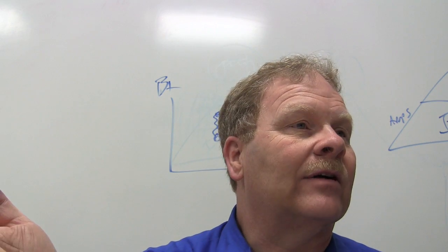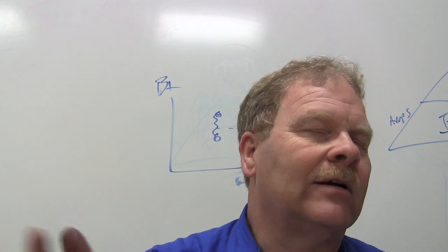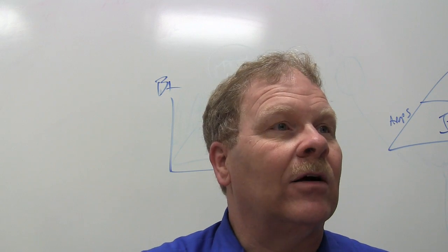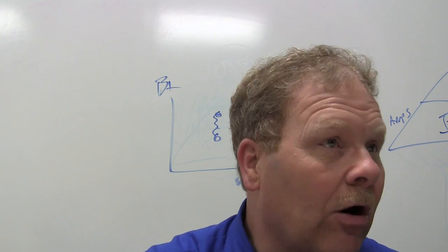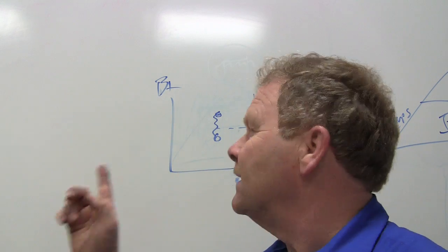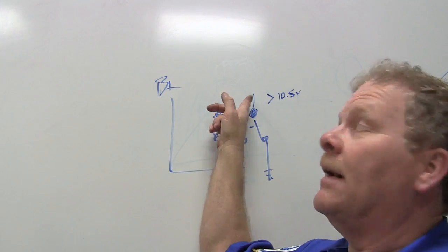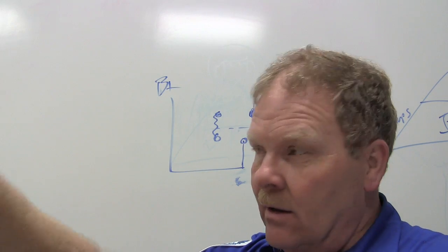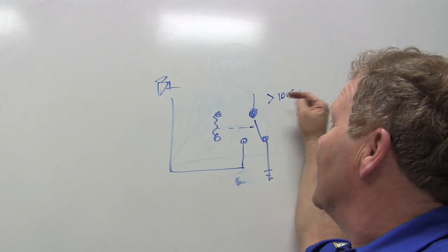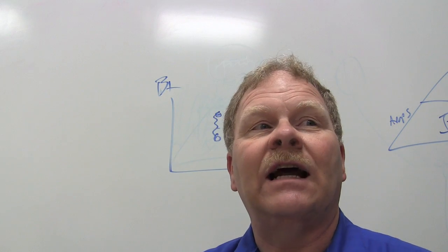And I went all the way to the end of that trouble tree, and it told me to replace something or do something that didn't fix it. I can't remember what it was. And I said, I have lost something. I lost my way somewhere. I've gone off the straight and narrow, and I'm stumbling down the broad path to not be fixing the car. All right. So I says, I need to go back here, and when I looked at this schematic I figured out that this needed to be pulling a load, you know, there needed to be enough juice coming out of here to actually make things happen. Components were energized by this relay. I took my test light and connected it, and when I hooked the test light up to it, it wouldn't even burn the dadgum test light. But that meter was telling me there was 10.5 volts there.